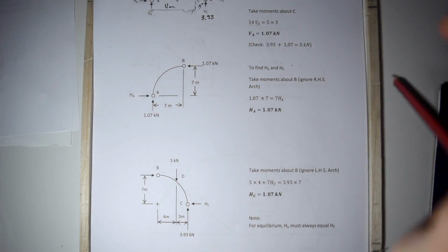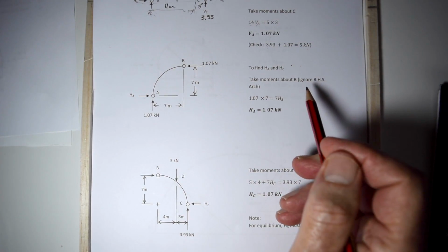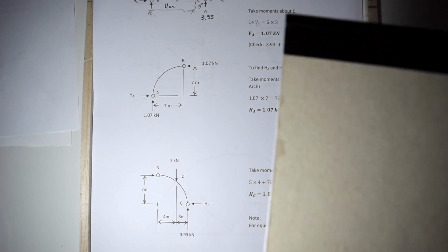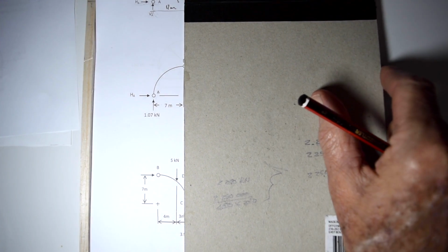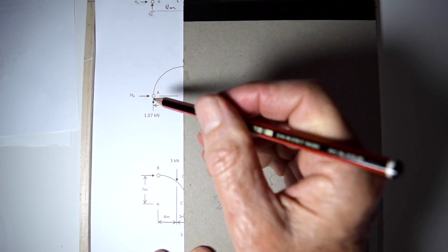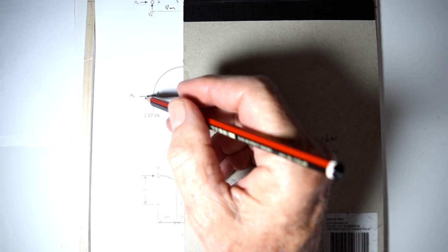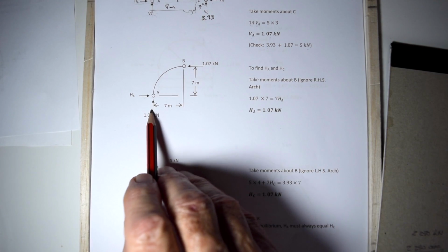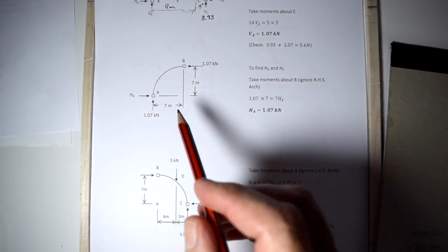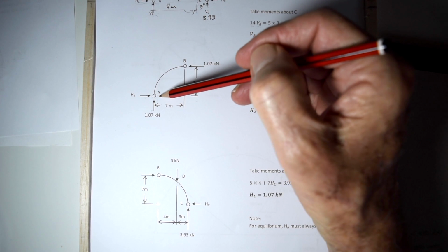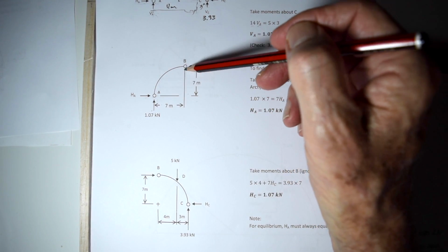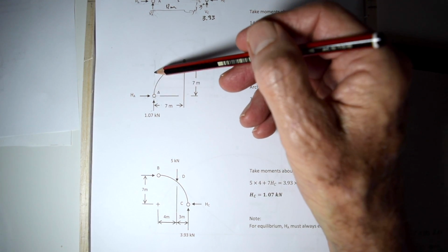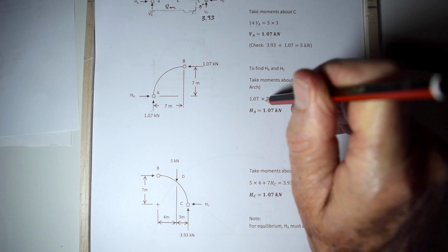To find HA and HC, take moments around B to find HA, and we can ignore everything to the right of B, like that. We're going to take moments around B of these two forces, and the only unknown is HA. So we've got 1.07 times 7 going clockwise around there, and you always measure this dimension at right angles to the point you're taking. You don't measure any other dimension. That force is acting up like that, so that's the distance. That's why that's 1.07 times 7